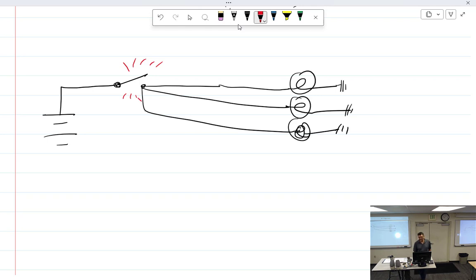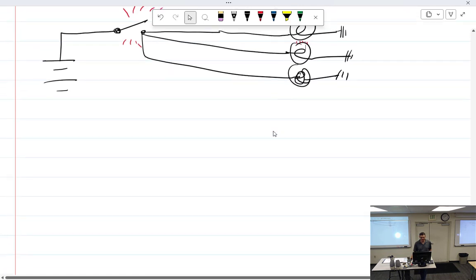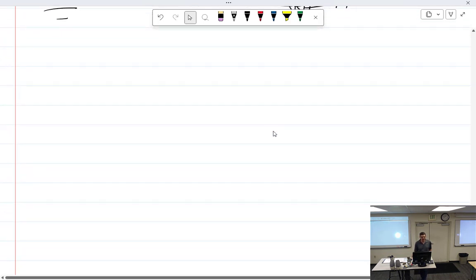And the lights were not real bright. Why not? Because all of the energy was being turned into heat at the switch. All of my battery was being turned into heat energy in my switch. It's great in the wintertime, I had a little auxiliary heater right there. Couldn't see outside. So somebody said, well, you should install a relay.